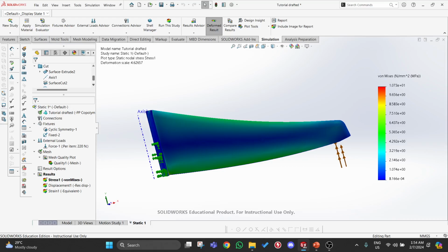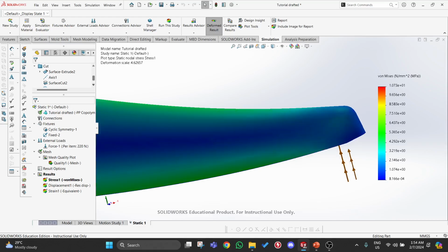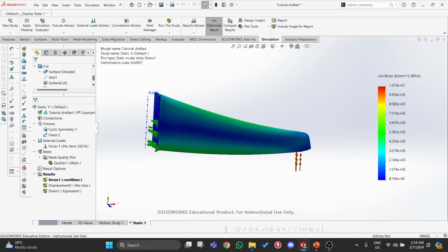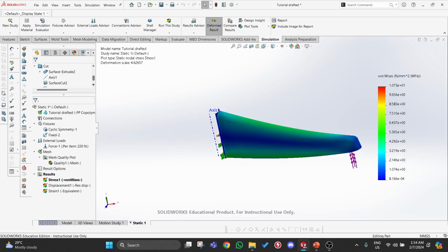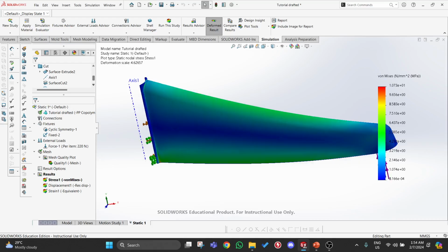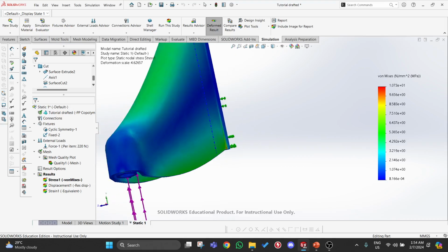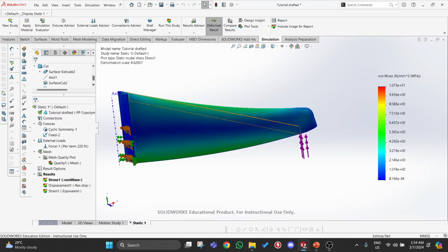First thing first, as I've stated previously, you see the distribution of the stress on your entire part. And as you can see, this is a pretty well distributed one. It still has a lot of negative space, which is the blue area here, the low stress area. Low stress area is not good because it's wasted space that is not being used. So it's best if you can get it mostly towards a yellowish to green color.